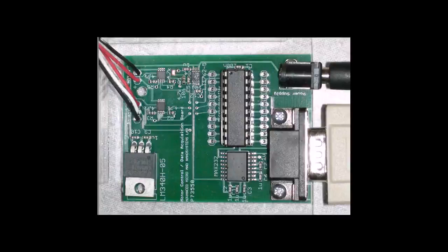When the host would like to retrieve the angle of the pendulum, it must send 255 to the microcontroller. When this value is received, the microcontroller performs an analog to digital conversion, reading the wiper voltage of the potentiometer. It then returns 2 bytes containing 10 bits of data representing the digitized voltage. This voltage is then multiplied by a potentiometer coefficient, which is the effective rotation of the potentiometer, divided by the maximum 10-bit value, 1024. The result of this multiplication directly represents the angle of the pendulum.